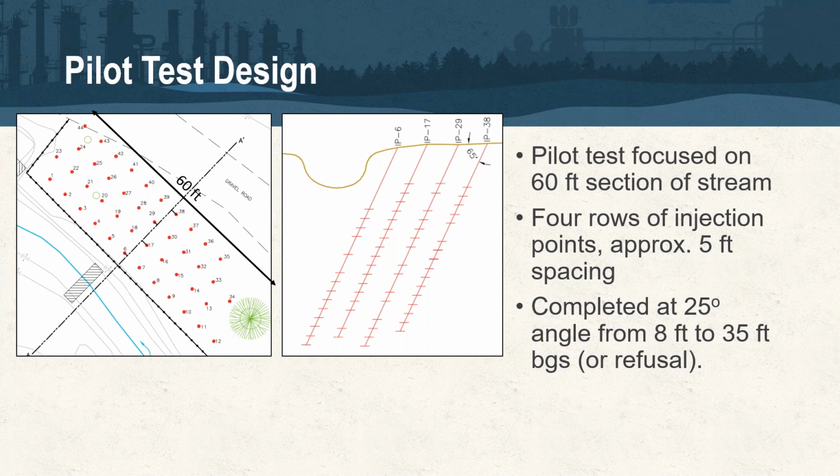Usually 5 foot on center to maybe 7.5. It's going to be a function of depth, and so injection point spacing is 5 to 10 feet for most sites, and that's going to be a function of the geology and starting depth below grade, because as your injection spacing widens, your injectate volume has to increase accordingly to meet the radius of influence that you need to match up with the adjacent location.